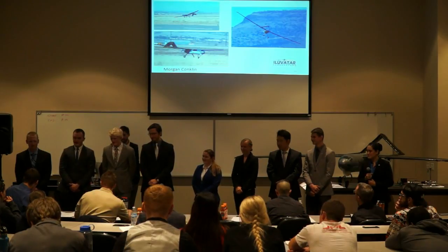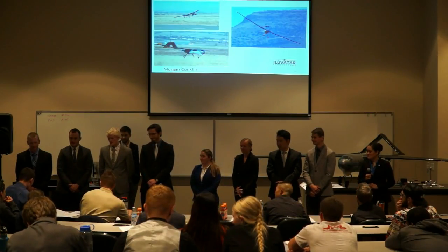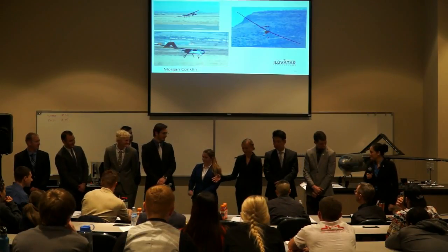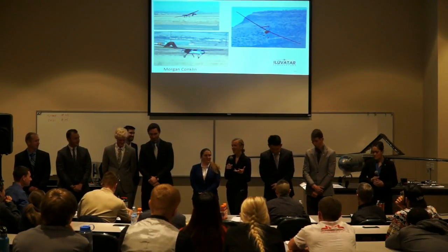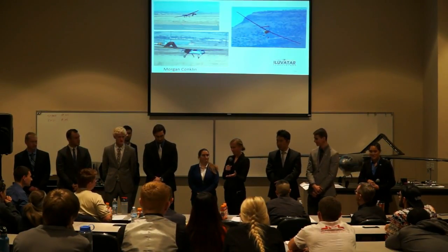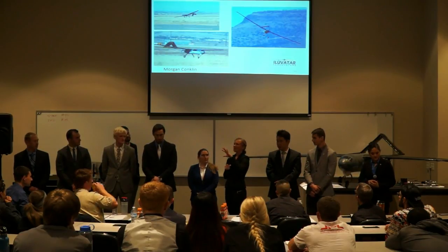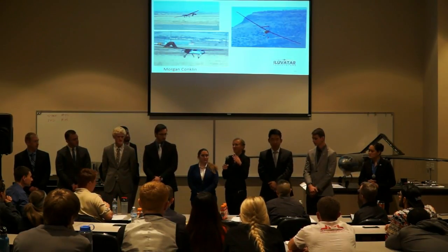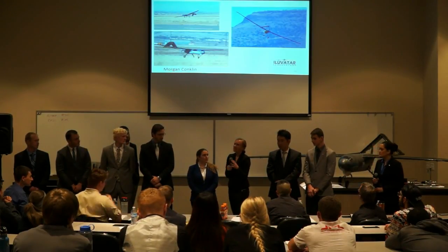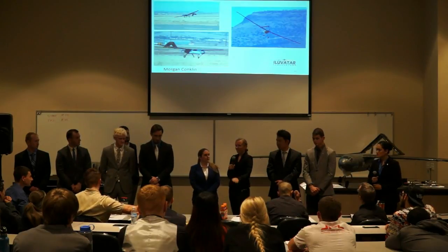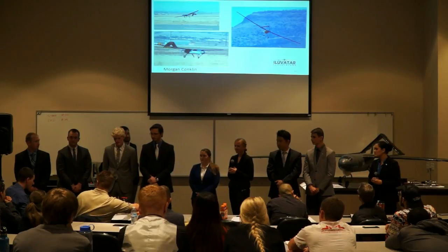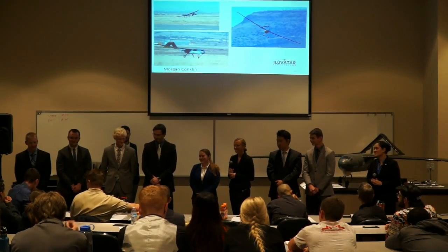So first off, this may not be the most intelligent question, but why an inverted V-tail? Morgan, do you want to take that? So the main driver behind that was our pusher propeller. We do have the camera on the front, and we didn't want the interference of the propeller on the front. So we put it on the back, but to ensure that the tail wasn't getting a lot of interference, we wanted to do something that would get it out and away from that. And then of course some of the other designs we looked at did incorporate a V-tail, so we went along with that. Okay. Just seems to me like you might get a little more control authority if your tail was actually in the stream, but I don't know these things.